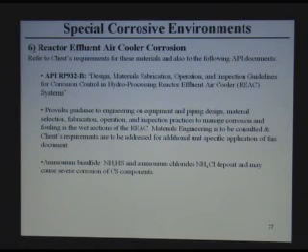So you have ammonium sulfides and chlorides, and you have water. So a very corrosive stream is formed in this cooler. And if you have high velocity and high H2S content, because this stream has a lot of H2S, you have the environment to cause severe corrosion, and disaster. A lot of fires happen from this air cooler.